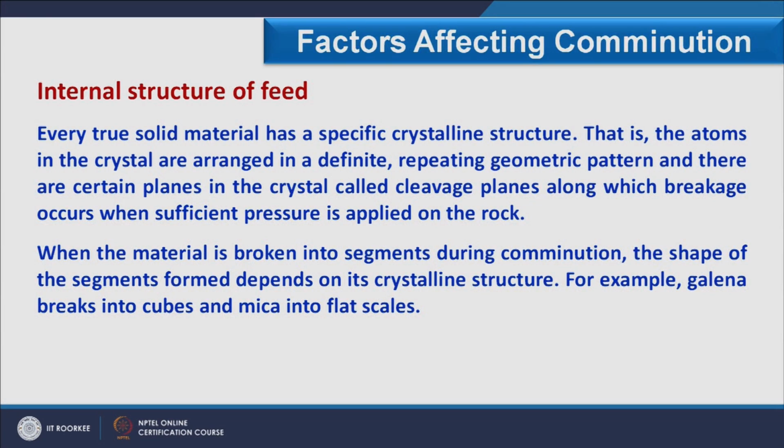When the material is broken into segments during comminution, the shape of the segments formed depends on its crystalline structure. For example, galena breaks into cubes and mica into flat scales, as we have just discussed. So, as far as the internal structure of the feed is concerned, if we put the impact or other pattern for breaking it, we have to target the cleavage pattern of the feed.